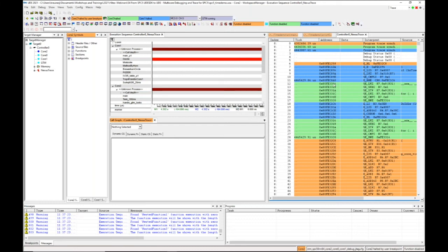If you are looking for more specific things in your application, then some of the SPC5 devices provide useful so-called cross-triggering mechanisms that you can use to specify trace sequences. So you can ask: if something happened on core 1, I'd like to start the trace on core 2, and after a certain time, I'd like to stop the trace and see what's happening on the target system.